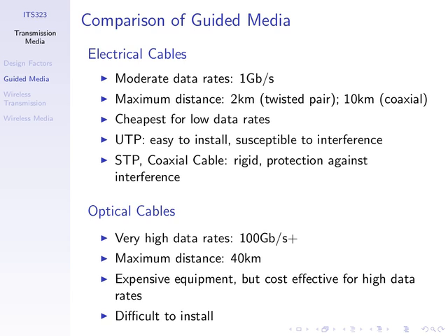Optical fibres, if you cut them like this, we could easily join them together? It's quite easy to join them back together manually. You can do it by hand almost, and you've got the original cable. If you cut an optical fibre, you need very special equipment to join them back together. So it's much harder to install optical fibres. So there are some of the trade-offs that are involved. They have different purposes. There's no one best technology in that case.